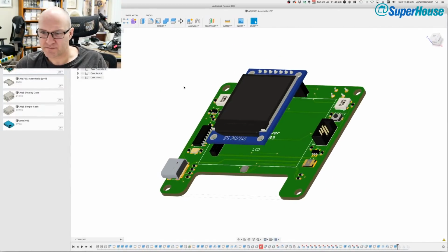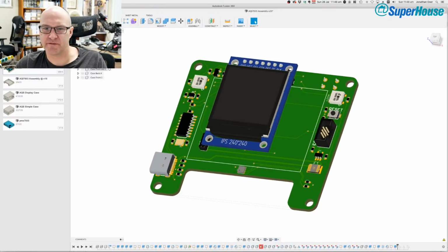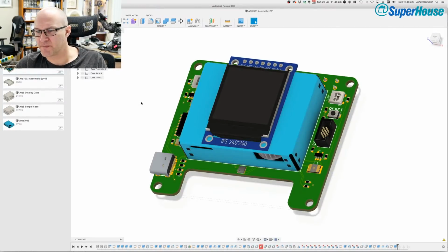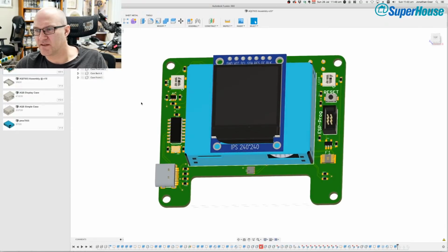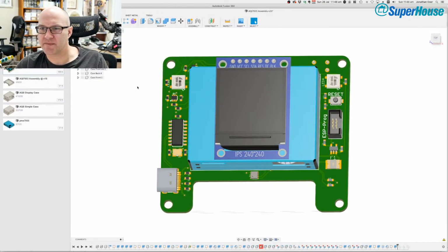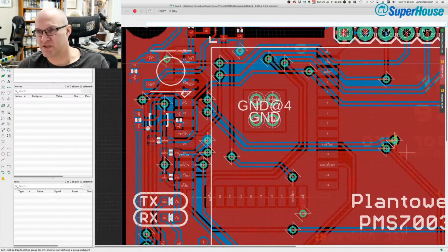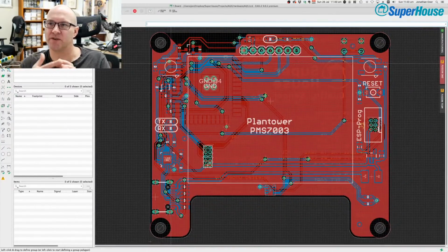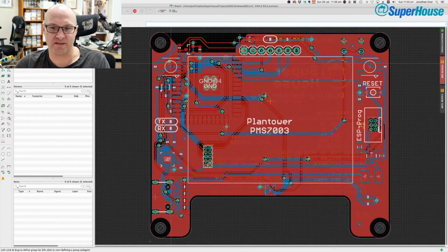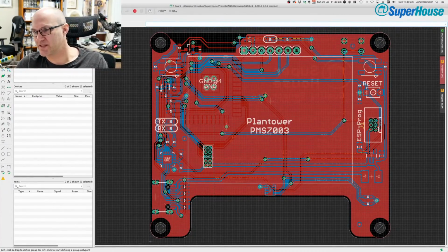And so this sort of view I've found is incredibly useful when it comes to understanding how things are going to fit together. If I'm in the PCB view, sure, I can extrapolate from this flat 2D view and think, okay, so I've got these addressable RGB LEDs up here. I've got them in the corners because I want the air quality sensor to be able to glow different colors depending on if you've got dangerous levels of something in the room. Say it detects that you've got a gas leak. I want to make the case flash red so that it's getting your attention.